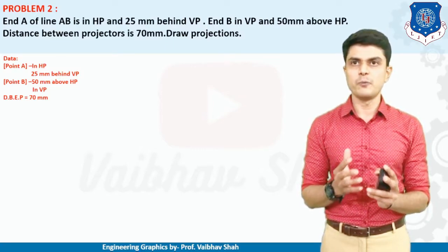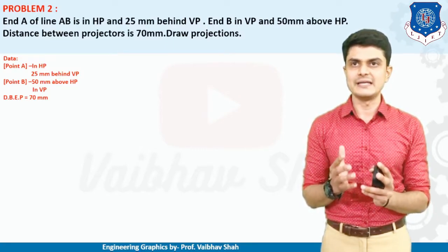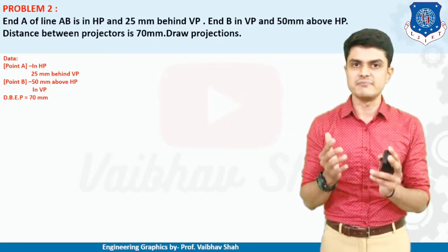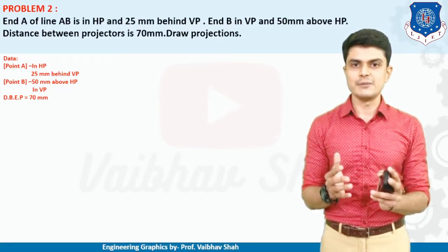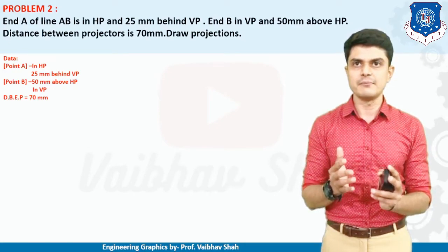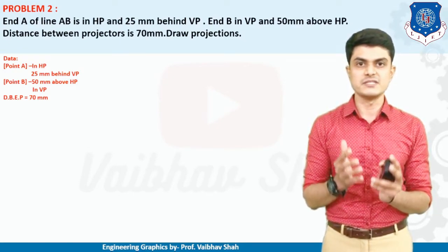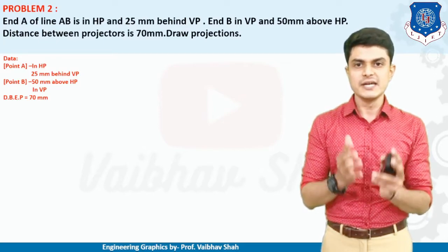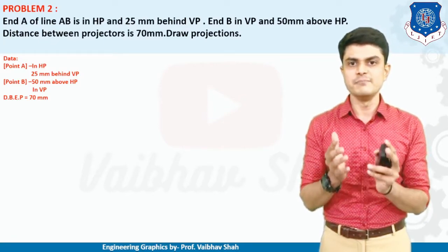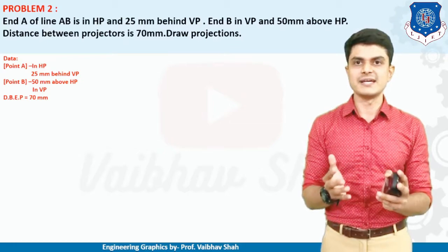So here 2 points positions are given. So point A is in HP, as you can see, 25 mm behind VP, and second point B is given, which is 50 mm above HP and in VP. And the new data which is given is the distance between end projectors. In short, you can write DBEP, which is given as 70 mm.